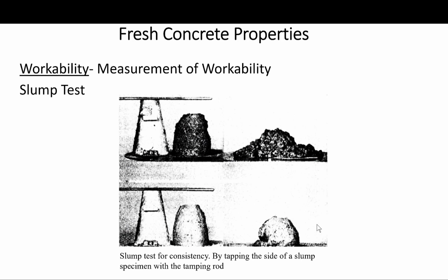Changes in slump on a given job generally indicate a change has occurred in the aggregates or in the amount of water or admixture being used. This should provide a warning that something is happening to the mix so that remedial action can be taken if necessary. Again, we are looking for consistency and uniformity.